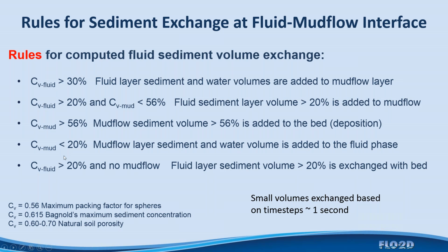So these are really small volumes. I mean, we're not exchanging like a foot of sediment at a time or something like that. We're talking about on the order of a second, which means that you're dealing with something on the order of less than 100th of a foot exchange. So the exchange is not impacting the flow hydraulics for the next time step, and so all of the hydraulics are uncoupled from the sediment transport. And I can do that because the Flow 2D model is so inefficient. It has to run on really small time steps.